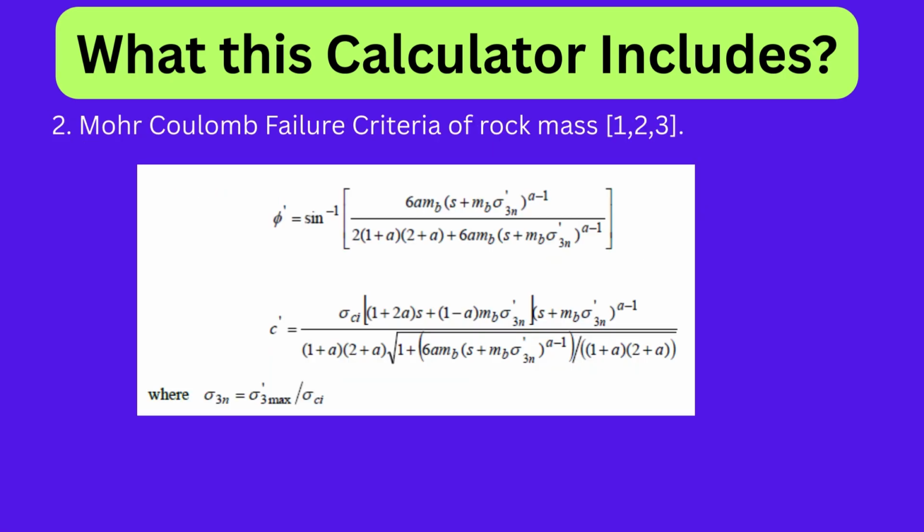Many geotechnical software tools use the Mohr Coulomb failure criteria, which means we often need to convert the Hoek and Brown rock mass properties into equivalent Mohr Coulomb friction angles and cohesive strengths. This calculator also helps in converting Hoek and Brown rock mass properties into equivalent Mohr Coulomb cohesion and friction angle. We can see in this slide the equivalent C and phi values of rock mass.